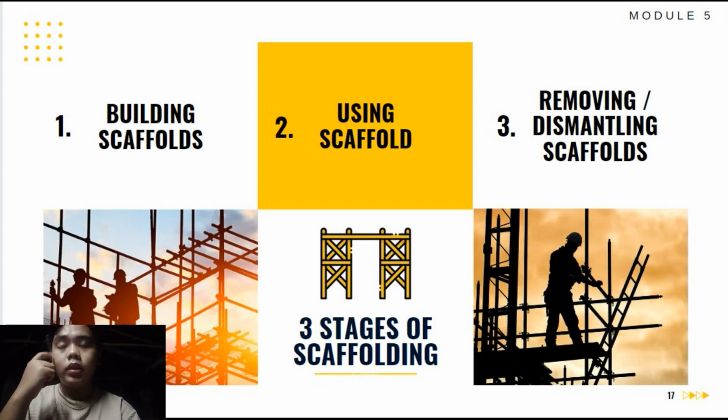Next one is platform. No paint on wood platform. Use scaffold grade wood, fully planked between front upright and rail guardrail support. Component pieces used must match and be the same type. Erect on stable and leveled ground.